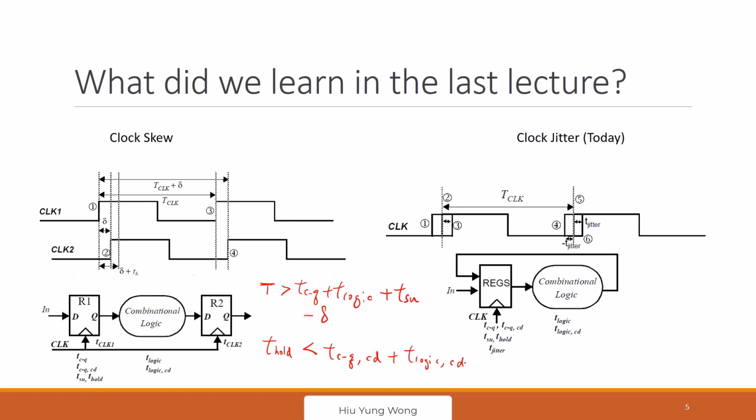But if you do it too fast, you still have not passed your car there long enough, your bicycle arrived already, you overwrite the car, right? And then you will fail. And with this skew, the worst thing is that it further requires you to reduce the hold time requirement, because the skew is saying that I'm going to take it later. I start counting the hold time later, right? So I need to make my hold time even shorter to avoid the problem.